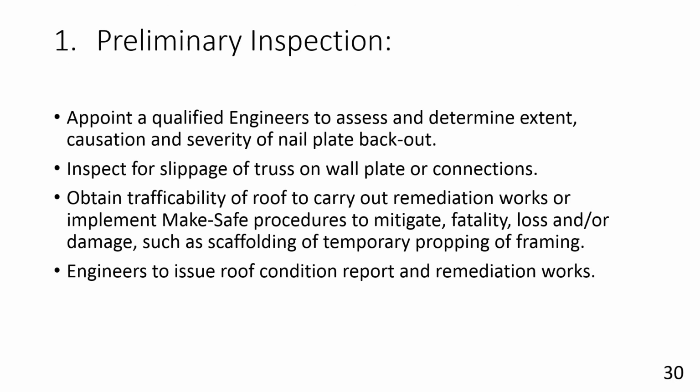In consideration of the technical skill and the severity of risk associated with truss failure, it is recommended that a suitably qualified engineer should be appointed to assess and determine the extent, causation, and severity of nail plate backout, and if necessary, provide a remediation scope of work and/or make safe to mitigate harm or further damage.